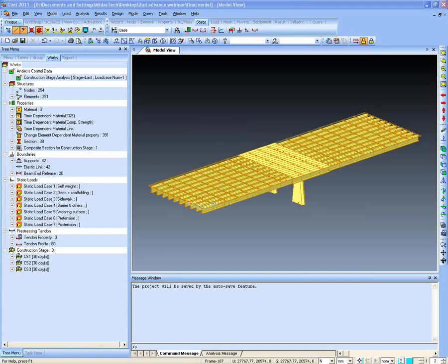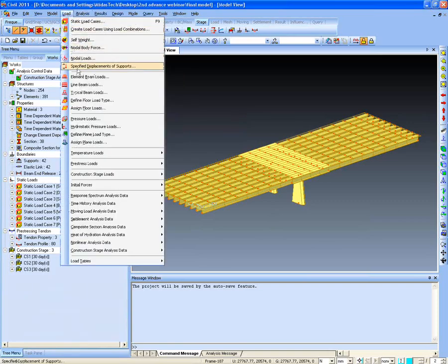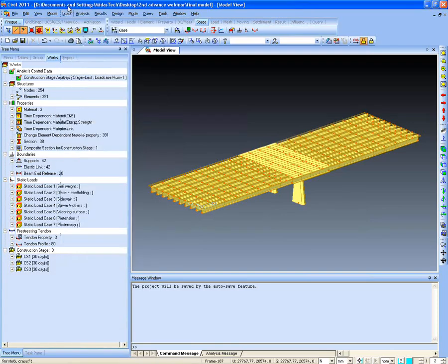Mr. Chandra, as I showed in my presentation, if you select the original type in the activation of the boundary, MIDAS Civil first brings the structure to the non-deformed level by applying force, and this is like applying specified displacement of supports load. So this is how internally the calculations are performed in MIDAS Civil.